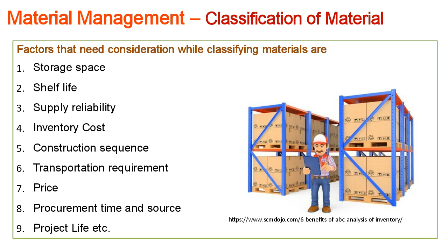So there are various factors which are to be considered for this. And even when a contractor quotes for a tender, they take some time to study the project, right? One of the important things they study is the availability of raw materials and their proximity to quarry sources, accessibility, and so many issues. These are of prime concern, and this influences the rate which they quote.